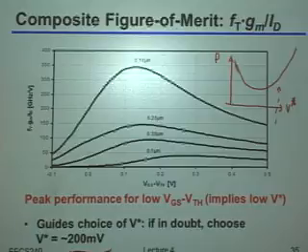Remember, V star just tells you directly the relationship between GM and ID. And if you increase V star, you're decreasing the GM you get per unit ID, right? So that means that if I have a fixed capacitive load I'm driving, then as I increase my V star, I just need linearly more bias current to drive that capacitive load. Okay? So now, what's happening on that side of the curve? Why is that side of the curve starting to come back up?